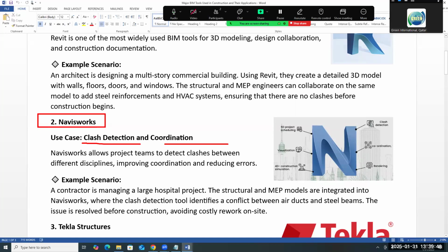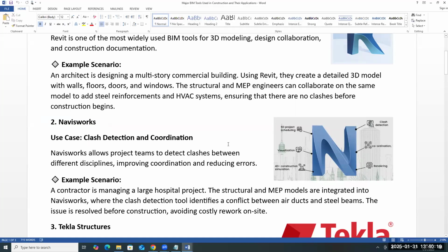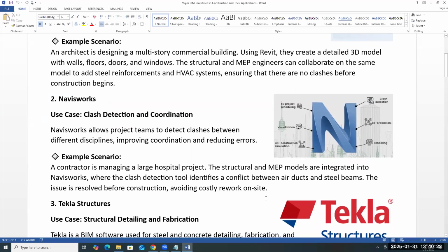Revit is where the people who design work, like BIM modelers: architectural BIM modeler, electrical BIM modeler or mechanical BIM modeler. The coordinator will collectively extract that information and put it in the Navisworks model, prepare the clash detection and write it up either to the consultant or the subcontractor. So that is another tool used, Navisworks, to prepare the clash detection and the coordination.